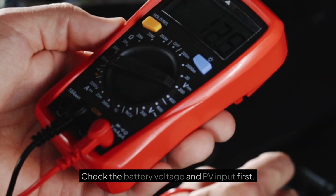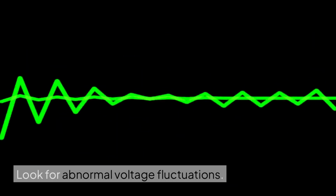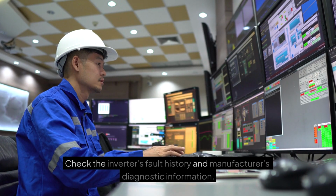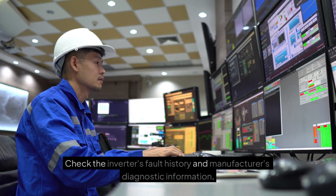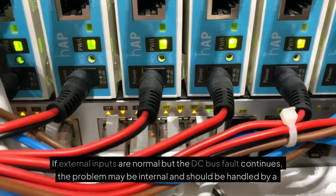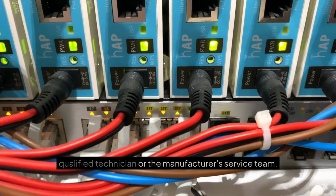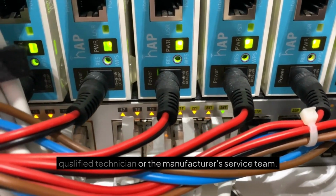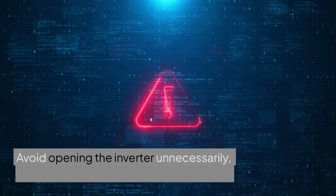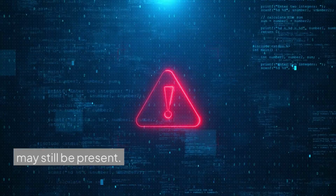Troubleshooting. Check the battery voltage and PV input first. Look for abnormal voltage fluctuations. Check the inverter's fault history and manufacturer's diagnostic information. If external inputs are normal but the DC bus fault continues, the problem may be internal and should be handled by a qualified technician or the manufacturer's service team. Avoid opening the inverter unnecessarily, especially when dangerous DC voltages may still be present.